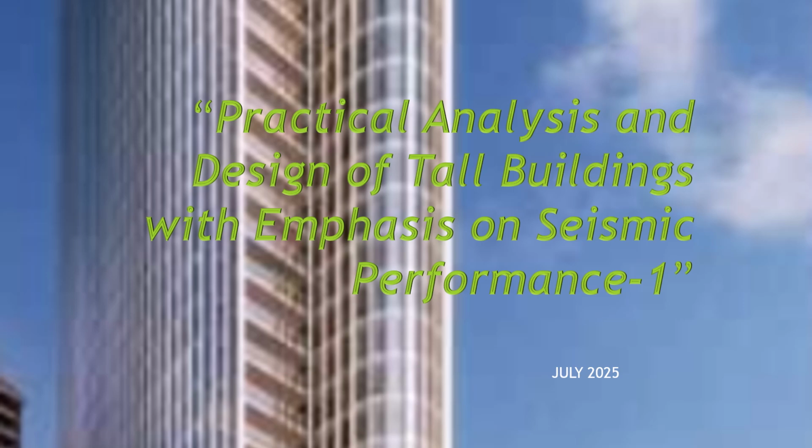In this lecture, we will walk through the practical seismic modeling workflow for tall building core wall systems. The goal is to show not just the software steps, but the engineering reasoning behind each modeling decision. This includes stiffness modifiers, mass definition, response spectrum scaling, and interpretation of analysis results. The discussion is based on CSA recommendations and common industry practice for performance-based design of tall buildings.